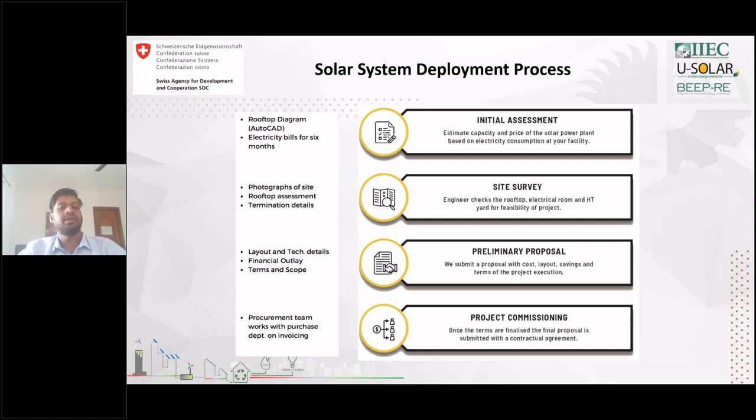So we know one thing, that the sanction load will determine the load which is available in your industry, and the roof space will be the other factor which will determine the capacity of solar which can be applicable. And there are a few state policies which define this too. For example, we have net metering policies in most of the states in India, but it is not adopted by every state. And the net metering policy differs from state to state. Individual states will have their own solar policies.